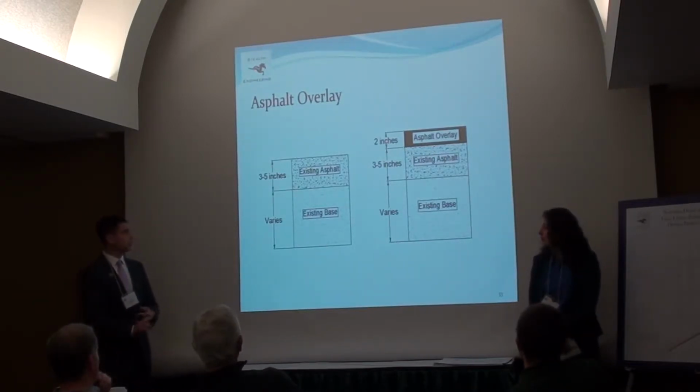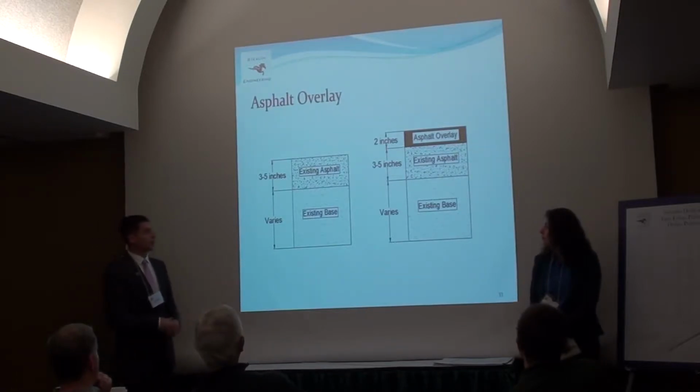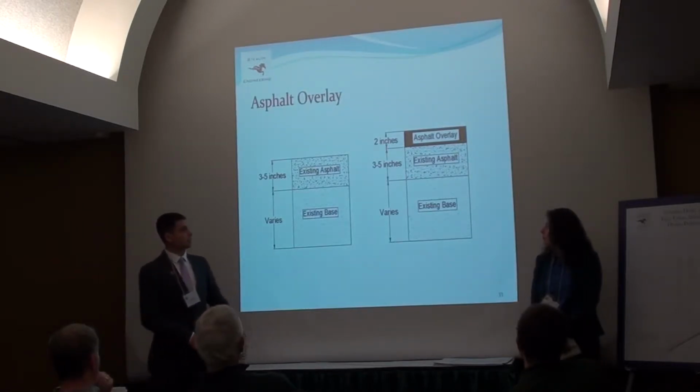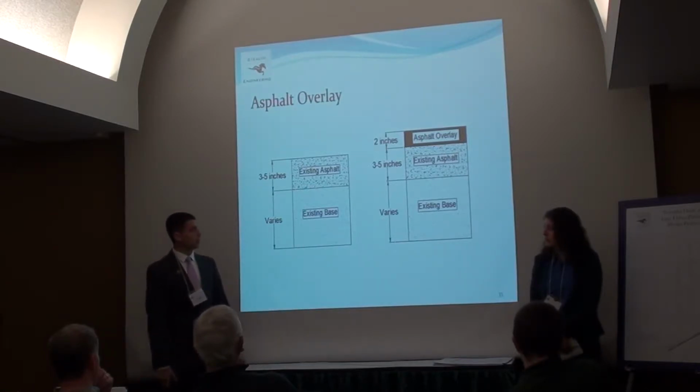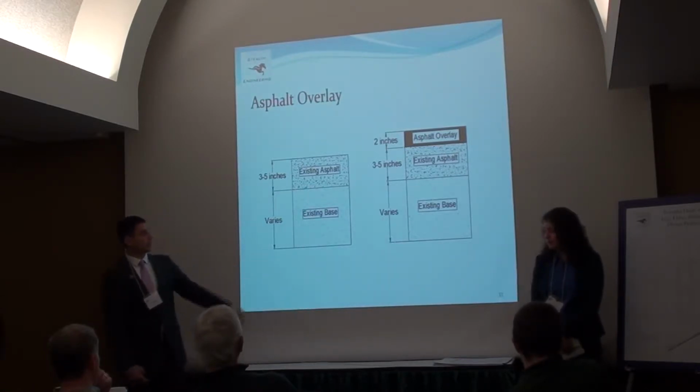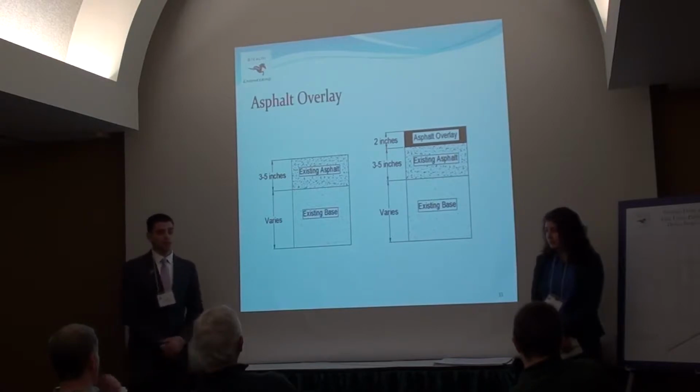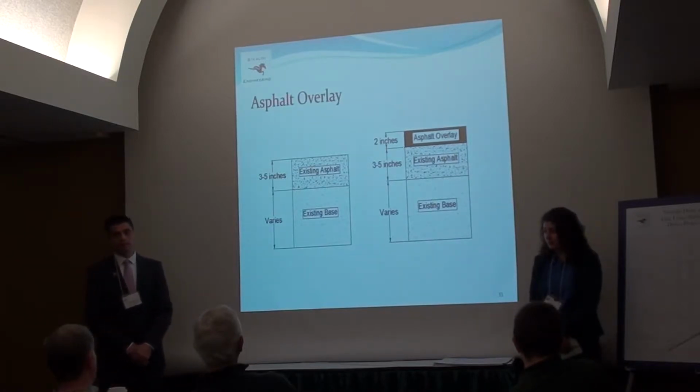In the existing cross-section, the base is buried. Based on construction and other ordinances, a 2-inch overlay is being recommended on top of the asphalt following minor repairs to the current pavement surface.